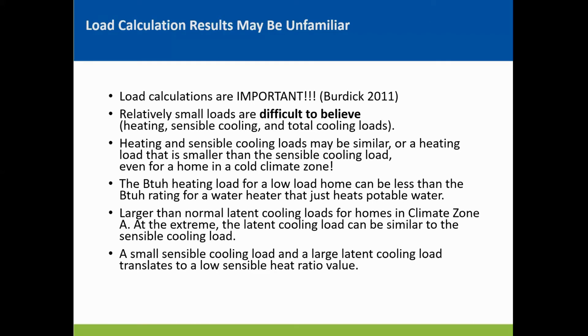To put it in perspective, the water heater could have more of a heating load than the space heating, than the space loads. And we talked about the latent loads being close to the same and sensible loads being much smaller. So your sensible heat ratios are going to be around 50%.